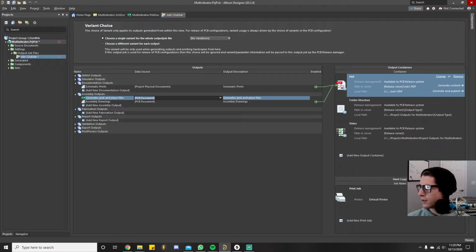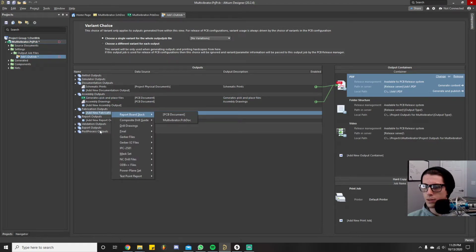So just heading down the list, we're on the fabrication output section now. So we're going to generate Gerber files and NC drill files. So let's see, Gerber files. So I'll pause here. These are probably some of the most important files, and if I'm not mistaken, the industry is making it to where you can almost generate an entire PCB fabrication package. You can get all that information packaged into one elegant file, like a Gerber file, I think is sort of what it's going to.